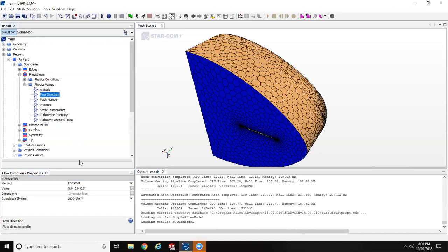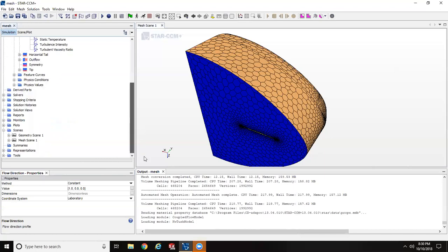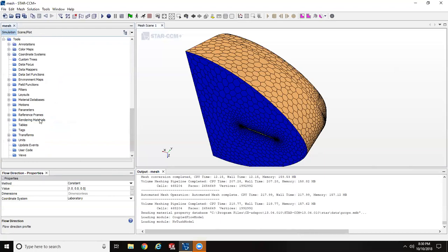Now our flow direction right now is just set to 1 0 0, so it's going to come in along the x-axis. As you remember from before, we used a table to do that. Well, right now when you're coming in from scratch, that table doesn't exist. So let's go get that table. And if you have your previous solutions that had the template in it, that table exists, and you can just export that table and then read it back into this solution.